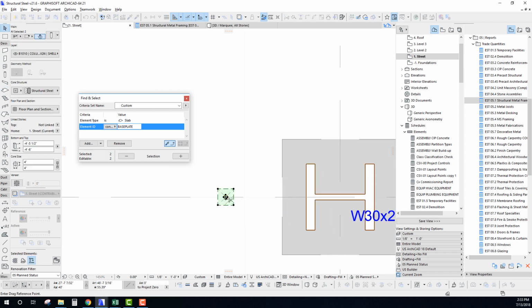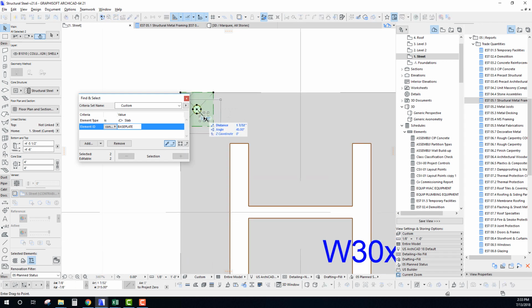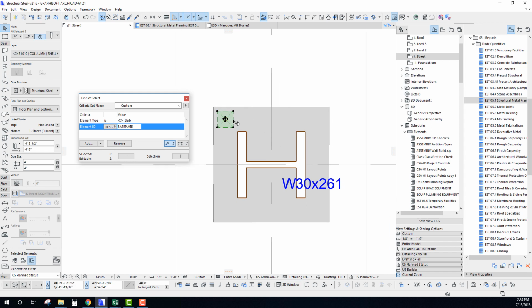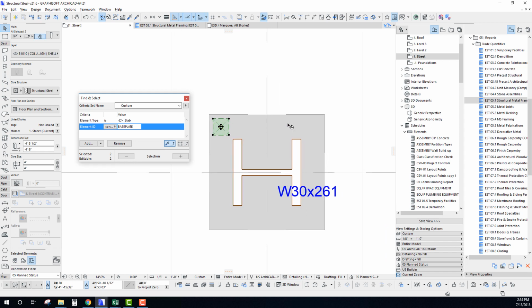And there's probably a bunch of different ways that we could actually draw this in. I'm going to offset this maybe 2 inches from our side, 2 inches from our side here. And who knows, maybe let's just go in our X direction, let's go 1 inch. Our Y, let's go -1 inch. We'll just inset that slightly.